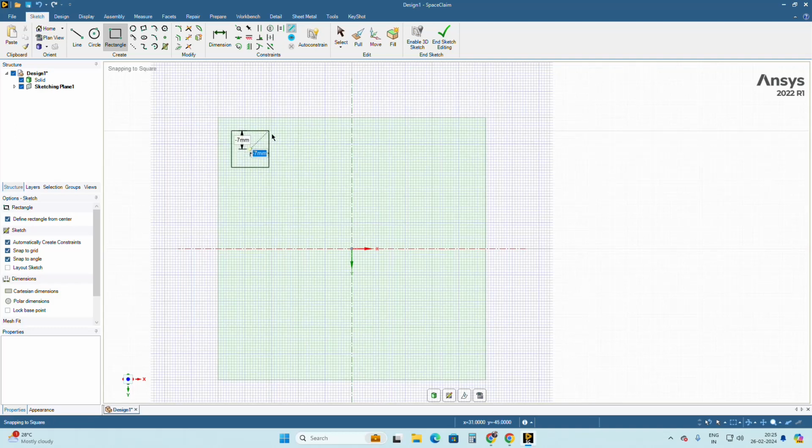After that I have to define the dimension of this rectangle. Here also you can enter the dimension. Here both are giving negative, right? So you just enter your desired value, I'm making it -8, press the tab option, and here also I'm making -8, and once I press enter, I have already created the rectangle. So like that I have to create a rectangle for the four sides.